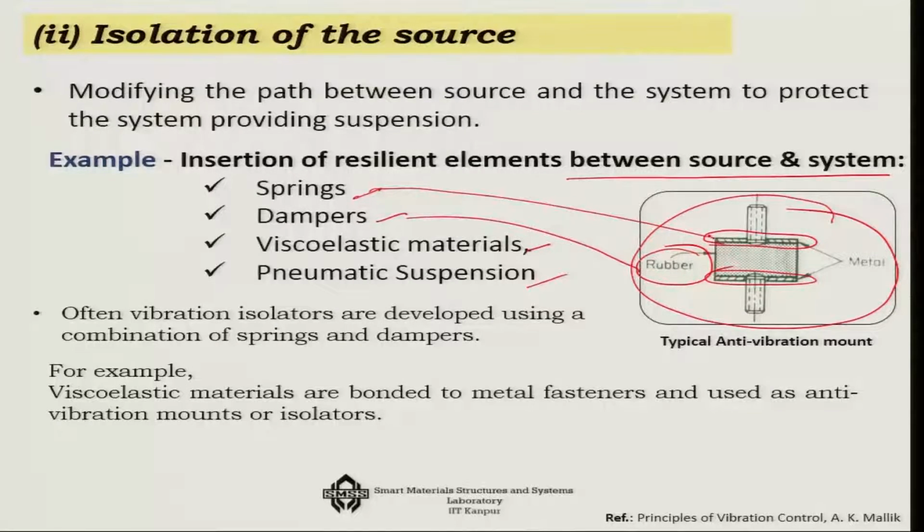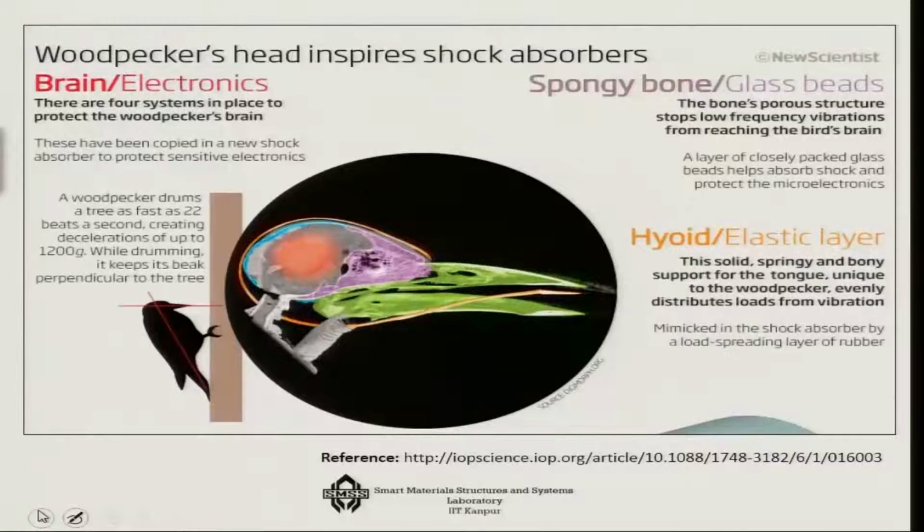And then there are studs with which you can fix it. So, essentially you can use this type of a system as a combination of springs and dampers, for vibration isolation from a noisy source to the system. We will call this viscoelastic material based isolation, and we will later talk more about this kind of material properties.